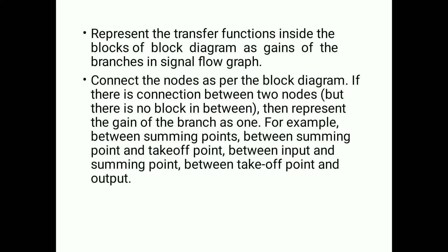If there is a connection between two nodes but there is no block in between, then represent the gain of the branch as 1. For example, consider between two summing points, that is between summing point and takeoff point, between input and summing point, between takeoff point and output.